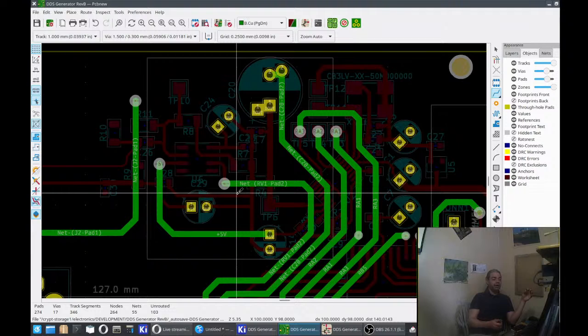And they come in two different sizes, even though the package is the same dimensions. And when you're ordering parts, you might just overlook the pin pitch when you're going by dimensions. So you go, okay, well, it's that high, that wide, that's perfect. And you just keep going. Then you get it, and you're 2.5 millimeters shy, so it doesn't sit on the board and you have to kink it.